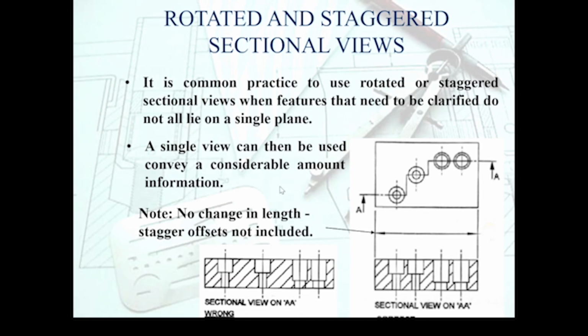There are a couple of different kinds of sectional views you may come across, and there are more than what these slides cover. So there are broken out sectional views as well, so it's something you need to be aware of, where we choose to just pick a small section and zoom that in and demonstrate the details within that small section. That's called a broken out section view.